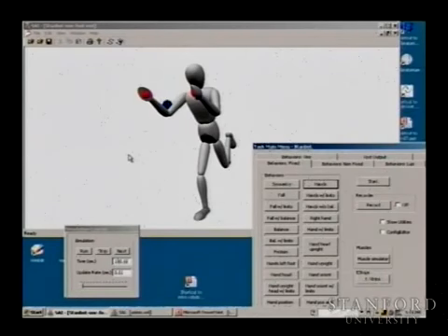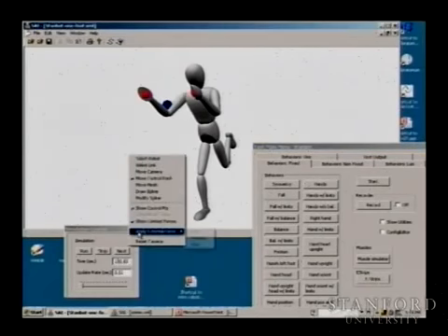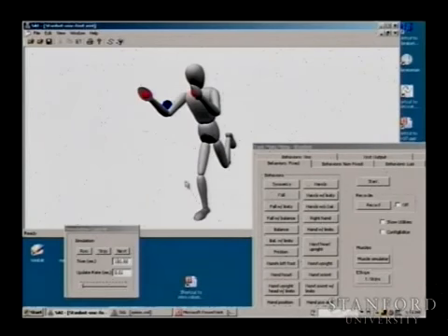In fact, this environment we developed is quite interesting. You can not only interact with it by moving the goal, but you can go and pull the hair. Ouch! You can pull anywhere. When I click here, I'm computing the forward kinematics and the Jacobian, and I'm applying a force that is immediately going to produce that force computed by the Jacobian on the motors, and everything will react in that way.